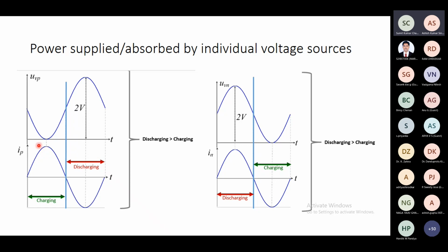With that direction, if I say that this is a charging instance, of course, here the voltage is always positive. The current polarity has changed here in the other cycle, so this must be the discharging instance. So the charging area or the discharging area will be more. The total volt-ampere product, volt-ampere second, in the first half cycle, which is for charging, will be high, or in the second half cycle, the discharging will be high.